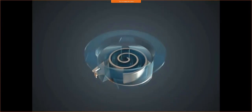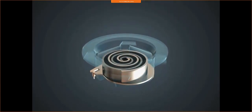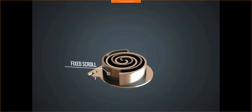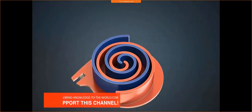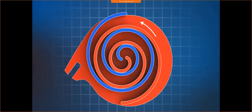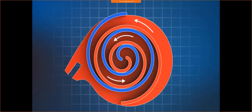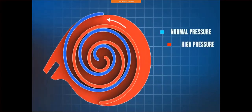For better visibility, only the moving scroll with its base plate and the fixed scroll are now being displayed. The gas is absorbed in the forming chambers and transported to the center of the scroll set. As the rotation progresses, the chambers become much smaller, so that the gas is compressed within the compressor.